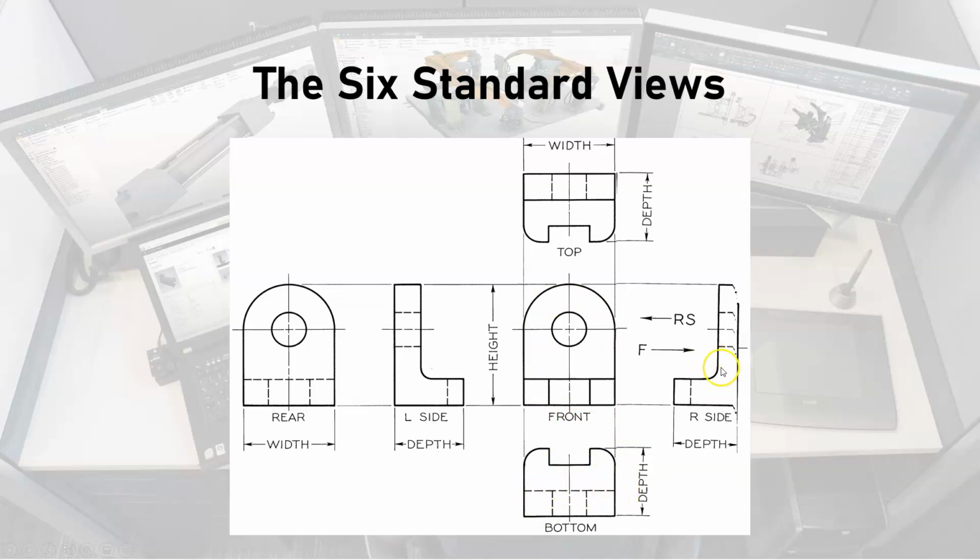So with the right side view and the left side view, they are in fact true mirror images, because there are no surfaces that are occluded or hidden that's not shown in one of the other views. And the rear view is, like the top and bottom view, a mirror image with some edges transposed from visible to hidden.